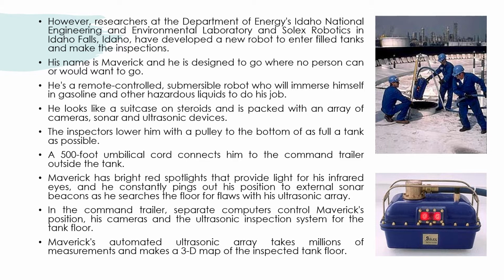In the command trailer, a separate computer controls Maverick's position, his camera, and the ultrasonic inspection system for the tank floor. Maverick's automated ultrasonic array takes millions of measurements and makes a 3D map of the inspected tank floor.